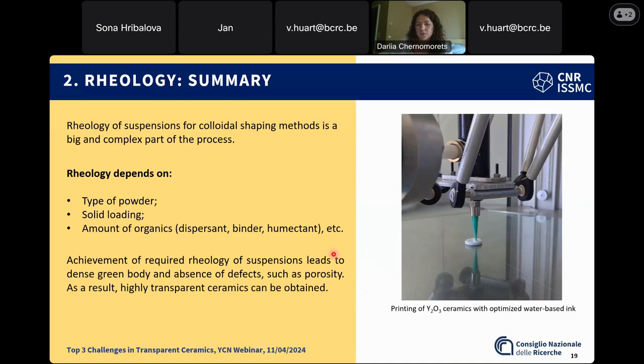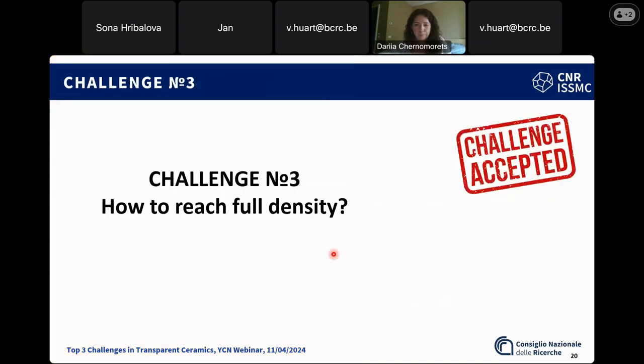first the lithium fluoride will help you with a liquid phase that allows the particles to rearrange and wet their surface. But then you do have some reactions, but eventually lithium fluoride should evaporate and leave. So you might have some small amount that remains if you don't use exaggerated amounts of lithium fluoride, of course.